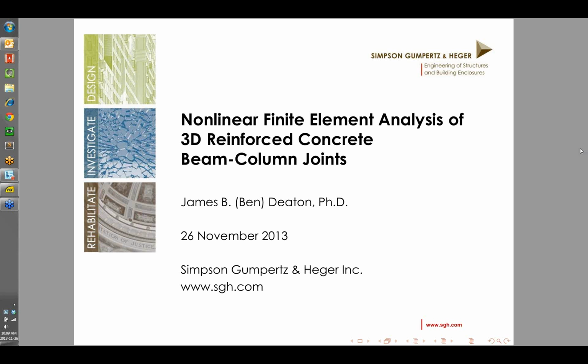Okay, here's a question. I think this is referring to how the steel rebar are simulated. So yeah, the steel reinforcements, I'll just review some of how that was constructed. The steel reinforcements can be embedded as either truss or beam elements within the concrete. And the steel reinforcing bar itself had a von Mises plasticity model with kinematic hardening.